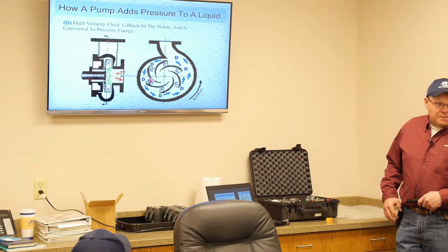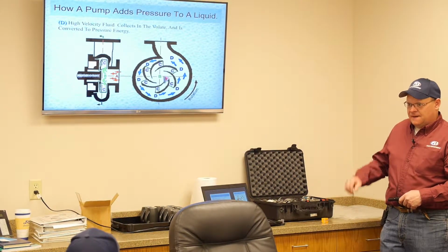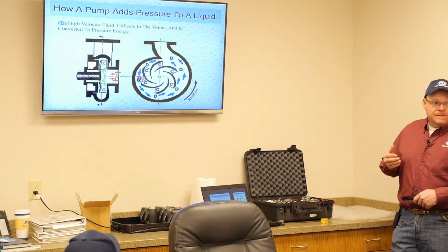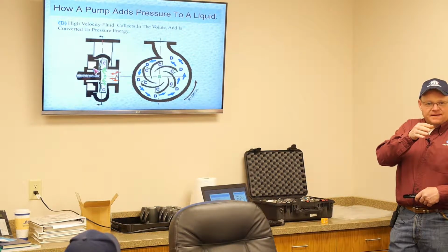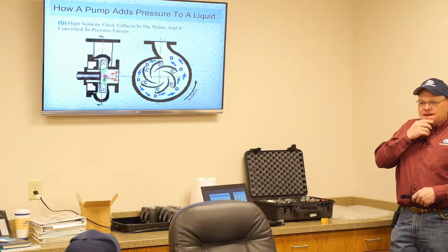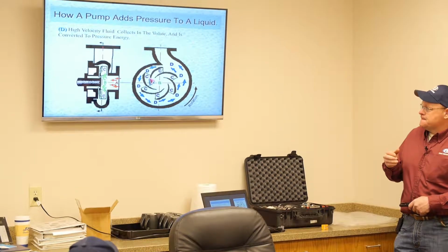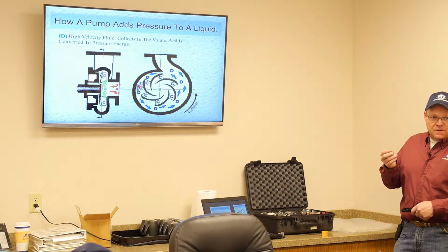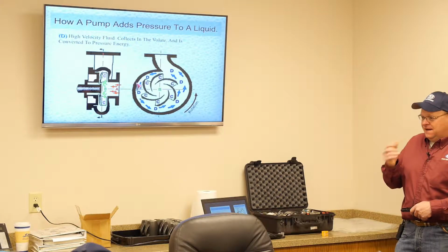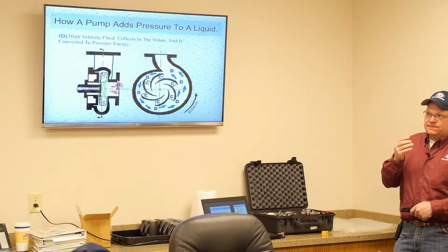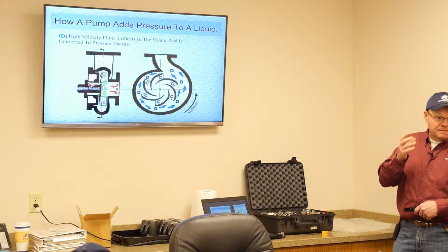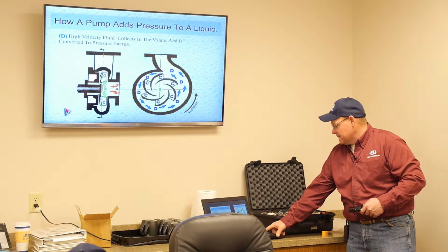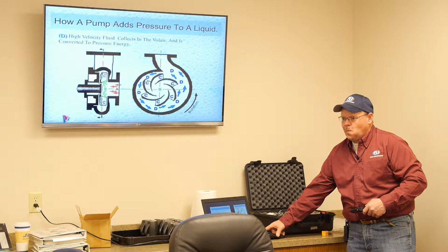So it'd be washed off in that. Yeah, and that cut water will be cut back. It'll cut a V into it, especially if you're pumping solids. You guys don't have a lot of solids laden stuff at Mears, but if you had anything solids laden that's abrasive, small particles of sand, anything, ethanol industry would be your mash that you've ground the corn in, it will reduce performance of the pump.